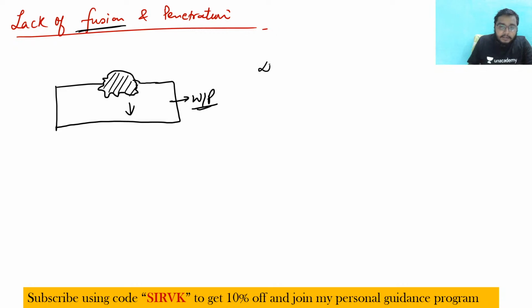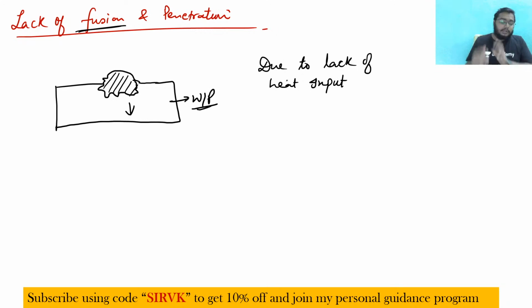So why is this happening? Due to lack of heat input. Suppose you haven't given the proper amount of heat input. If heat input is not there properly, the weld bead will not form properly. Whatever filler material you are giving will not melt and will not go inside, and definitely you will get a defect. Okay, what is the next reason?